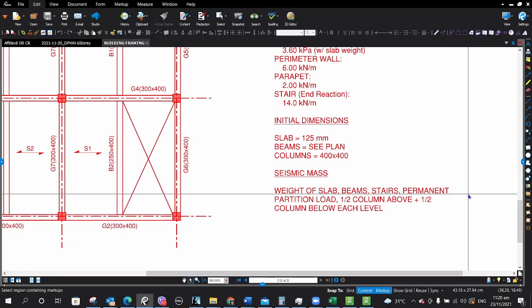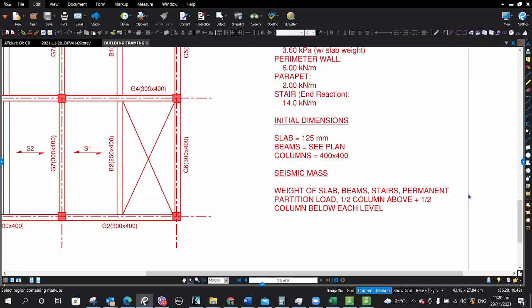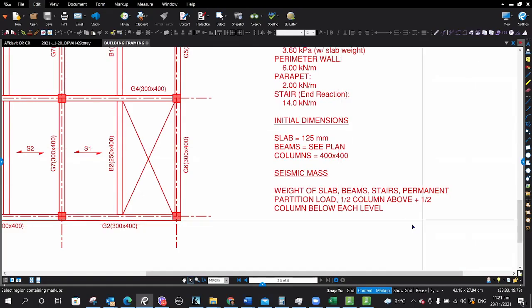That's the basic equation we will use. Similar to the seismic design of buildings, we adopted that principle, the inertia force from Newton. So part of that is you have to determine the mass, and then the acceleration is taken from the code based on the seismic hazard we consider. And then we'll discuss later the code-based seismic acceleration.